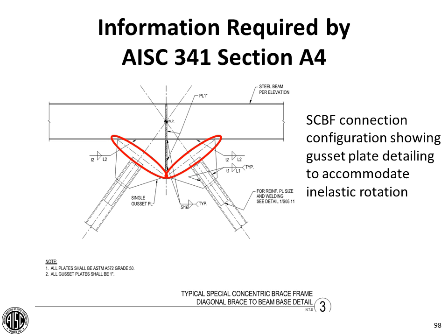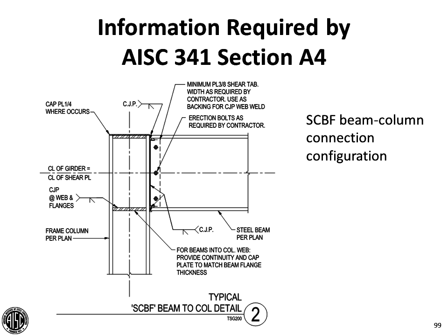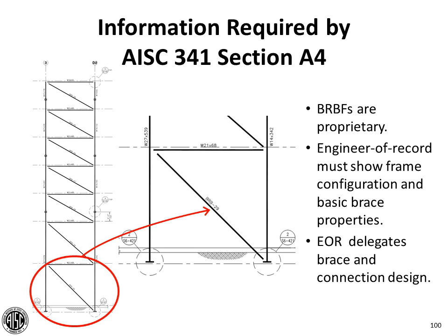Again, the example of this connection where the braces intersect the beam, again, the line that is to be free to be able to bend and allow this brace to be able to buckle out of plane has been identified. Beam to column connection for a special concentrically braced frame. Again, in this case, different from what might be required for a moment frame, a specific detail would be provided for that particular configuration.